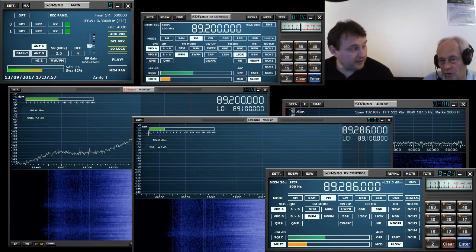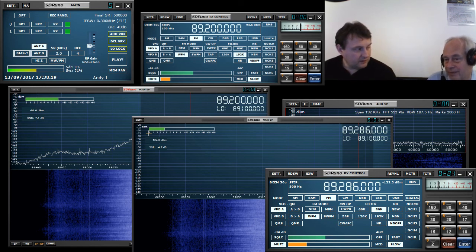And that's the local oscillator, which is the software equivalent of the traditional mixing signal, which mixes with the desired frequency that you're looking at. It's the difference between the local oscillator and the desired frequency that would traditionally be your IF frequency, if you have an IF. But of course in most cases you have zero IF, and so sometimes people get confused that the local oscillator ends up being the same as the frequency of interest. Right. Sorry. Yeah, absolutely.